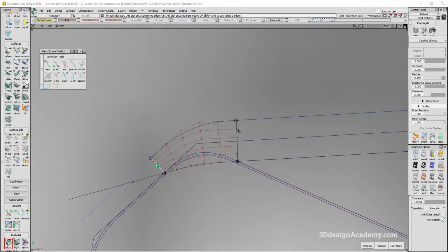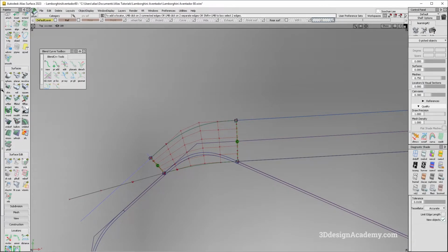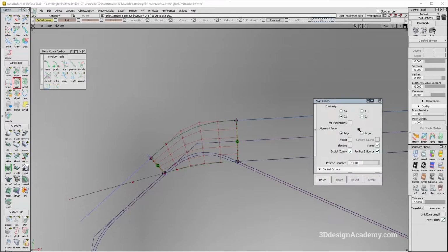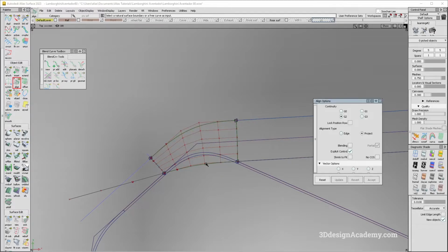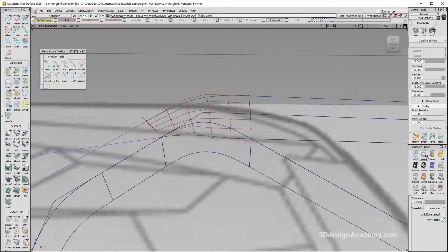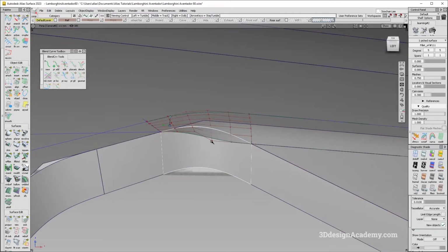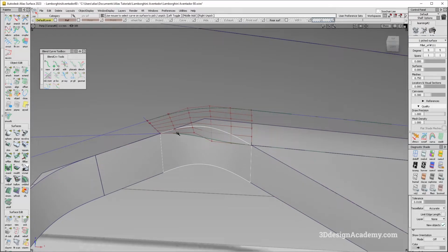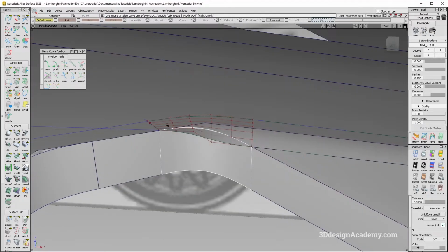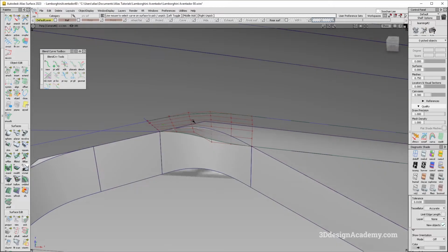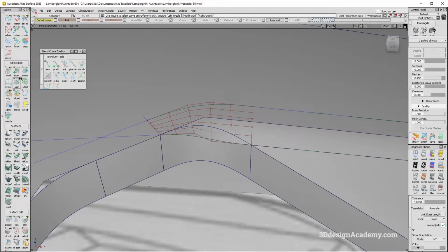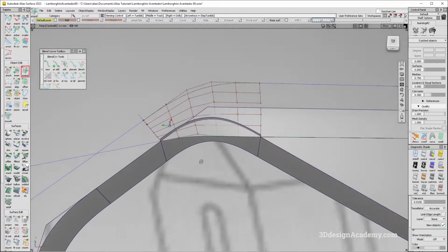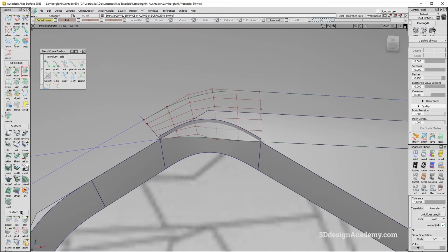And actually, let's turn those on, and let's use align to finish the side. So it's going to be G2 project. Like this, and there it is. That makes it nice and simple. I would say this one works pretty well in this situation because the angle difference is not that bad. If it was a sharper break, I think this might have a little bit harder time doing this, but since it's got a very gentle transition, I think this one works pretty nicely.